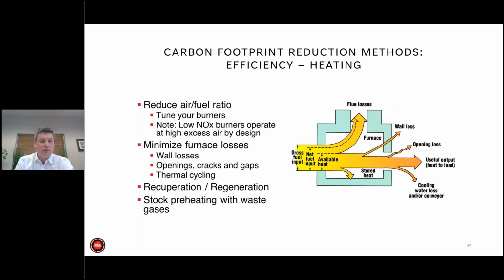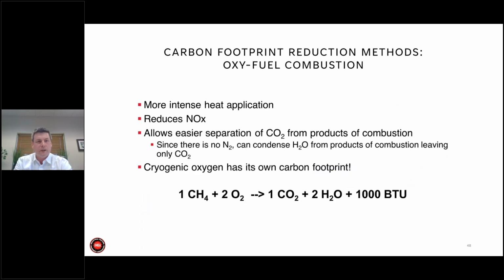And then use recuperation, regeneration, like I said, and do stock preheating with waste gases. There's lots of different ways to do that. If you want to talk to a furnace manufacturer, they can give you really good ideas of how you can do stock preheating with your waste gases and reduce the emissions that you have.